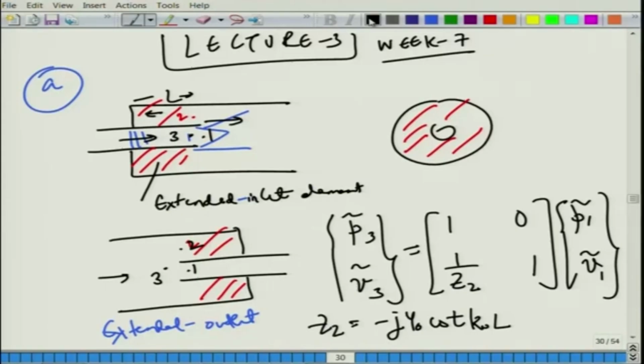Unlike in the case of a static medium, where there is zero mean flow, the pressure is constant like I mentioned and the mass velocity gets split into two parts. Here the stagnation pressure, the perturbation pressure, the convective pressure P c, not P tilde, P c tilde, decreases across an area discontinuity, because as the flow passes a certain change, a part of the flow acoustic energy is converted into heat or basically losses. So, that results in an increase in entropy.